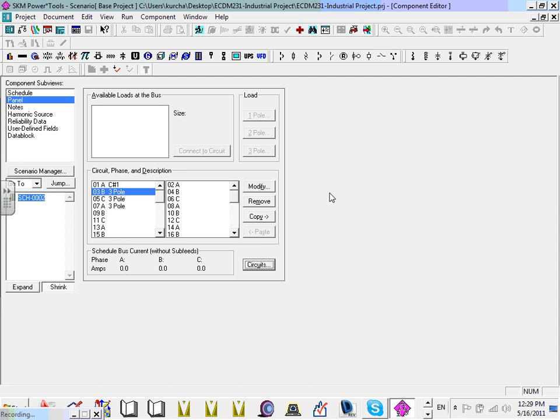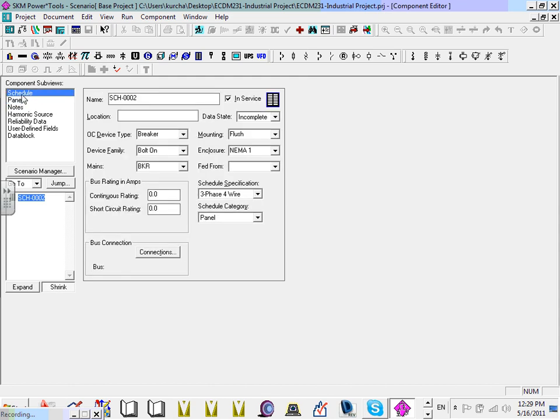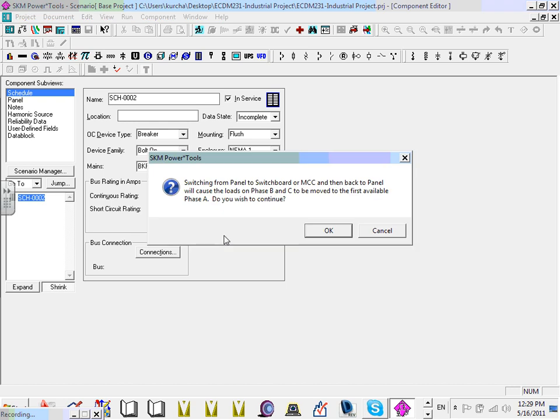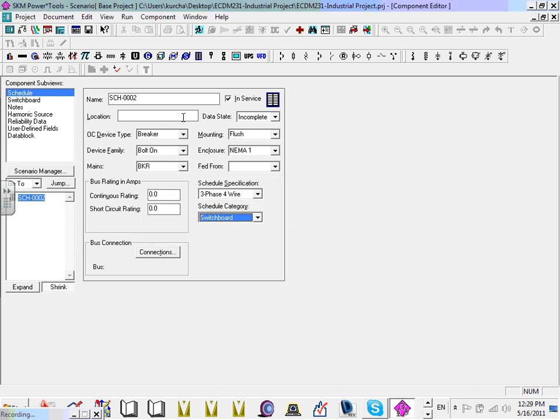If you don't want to use it to build the schedule, there is not a whole lot of value in using it to this detail. So you can build the schedule. The other one, guys, if you go to the top, it's schedule here. You can add a panel or a switch. Look at that. You have an MCC, switchgear. So if I need a switchboard, click on the switchboard. It'll change the format to a switchboard, and it adds all your switchboards in here, connections and so forth.